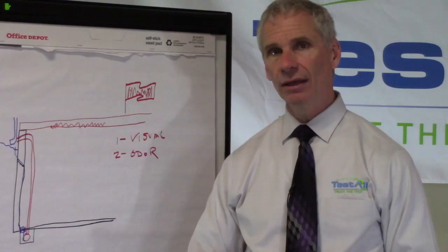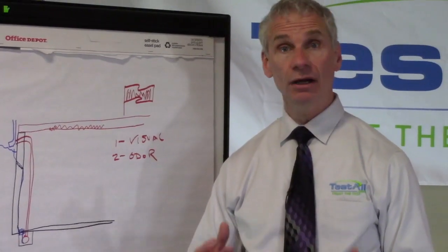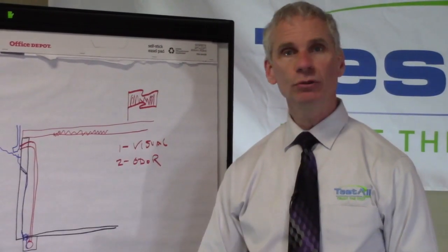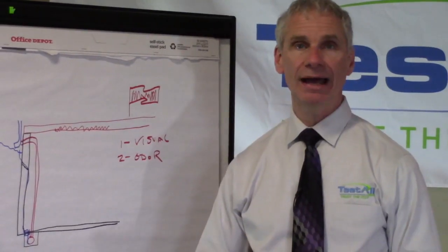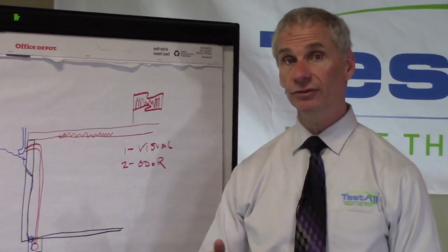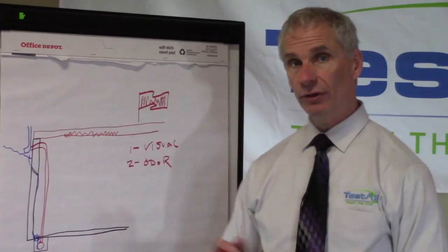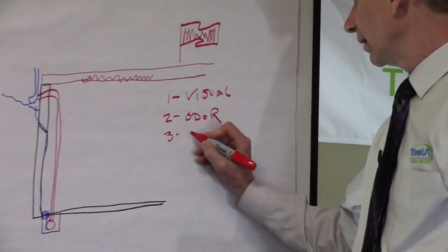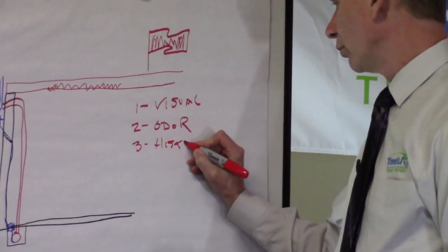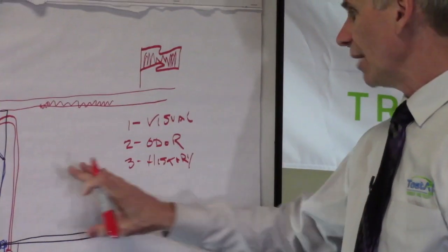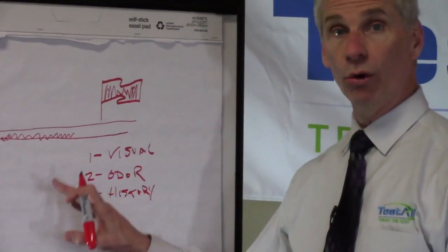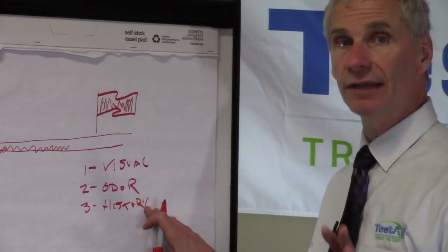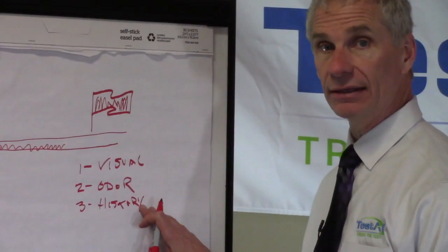It doesn't work that way because the odor comes off a solid. The solid are the spores. So when you get that damp, musty odor, it's mold. If you get just a dusty smell, then it's from the house just being closed up. So we need to understand the distinction between the two. So getting back to our red flags, we have odor and we have visual. The next one is history. If the owner or person giving you access, your client, to the home or building, and that building has a history of water issues, and they tell them to you, then that is a red flag.